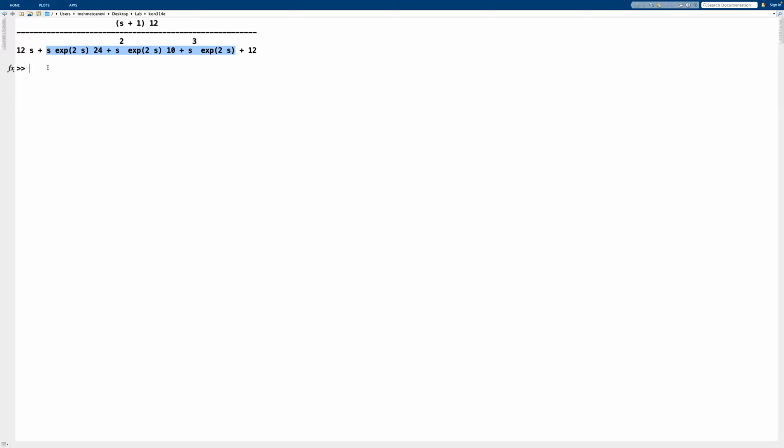So that's an issue, because all that we know to do is work with poles and zeros. We have dominant pole assignment. All we care about is to force two poles into a certain region, and we try to place all the remaining poles and zeros out of the dominant region, and we therefore conquer a system's behavior by doing that. But here we don't have a polynomial, therefore we are not able to calculate poles and zeros, so we're in a bit of trouble.